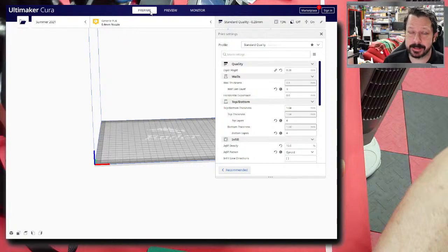Now, if you change things, so if you put a new nozzle in, put a new heater in, or if you change things about hardware on the printer, particularly related to the hot end, then yes, you do need to do PID tuning. Out of the box and no changes, PID tuning will have a minimal effect unless the environment that you put it in is very different from the environment where it was intended or assumed to be put.